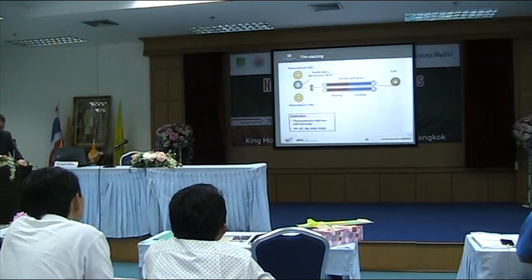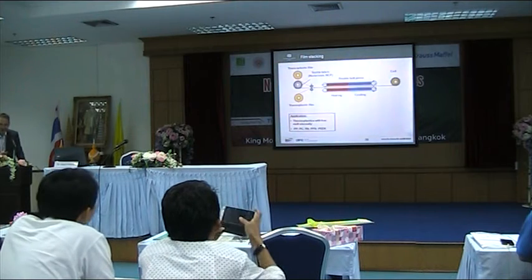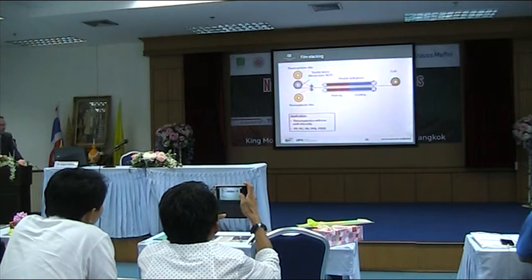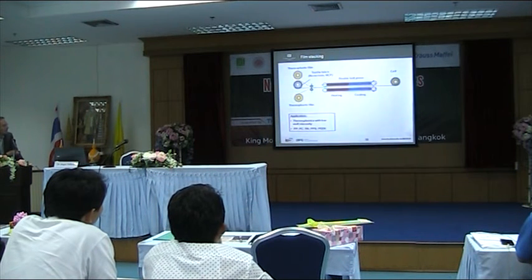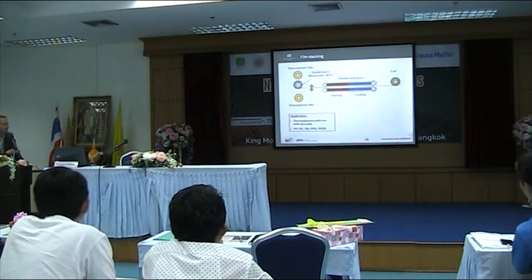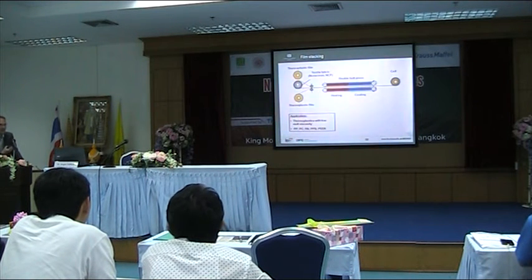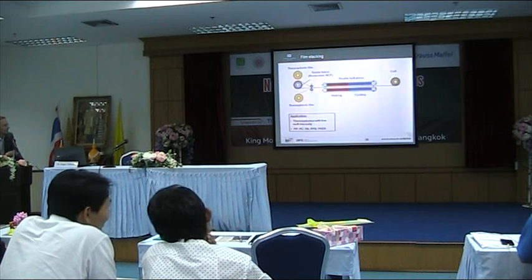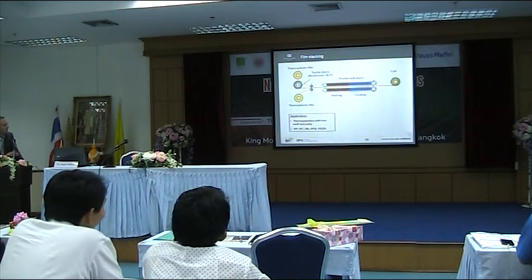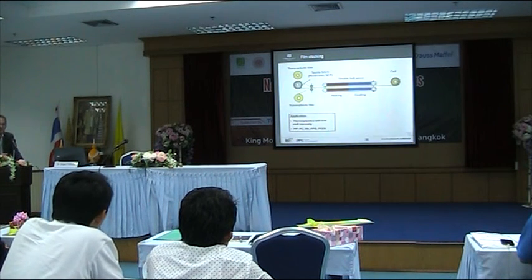So then we have some really detailed processes for making thermoplastic prepregs with natural fiber composites, with natural fibers. This is so-called film stacking. We have again a textile prepreg and have some thermoplastic film, and it goes also into a double belt press for consolidation with heat and compression, and you try to impregnate the textile prepreg with a thermoplastic film.